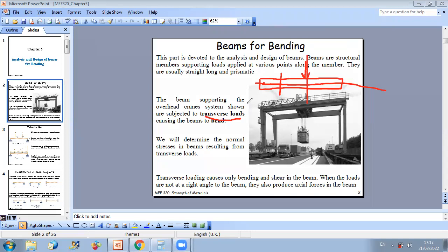Now, these transverse loads can result into bending and shear forces. In fact, whenever you have transverse loads applied to a beam, if you do any cut, you will see that in equilibrium condition, in the cross section, you will have development of a shear force and a bending moment. Now, the shear force will be created by, if you want, distribution of shear.